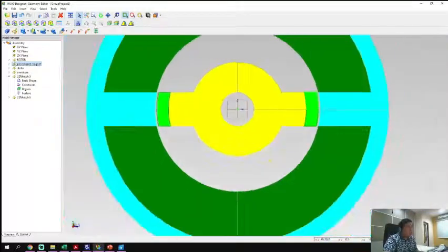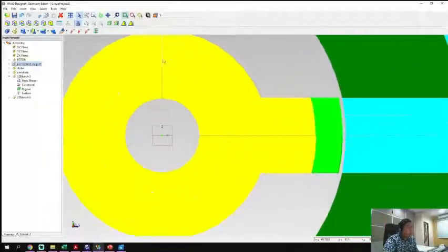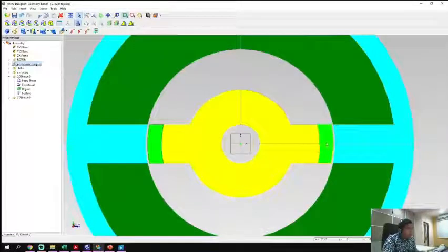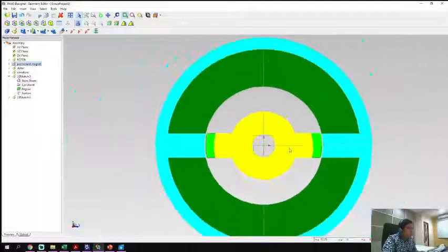As you can see here, we trim the upper part of it, of the 60 degree, and then we create a region, and the difference between the upper part and the lower part is the same, which is 12.5. And here you can see the line. So we create a region here, we merge it with the bottom, and then we use the y-axis reference, so we get the mirroring to the left side. So we get two perfect permanent magnets, as you can see here.